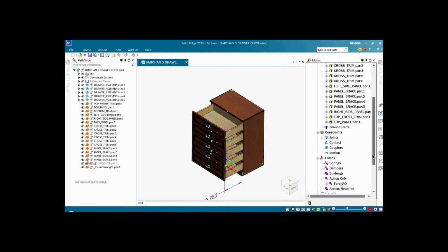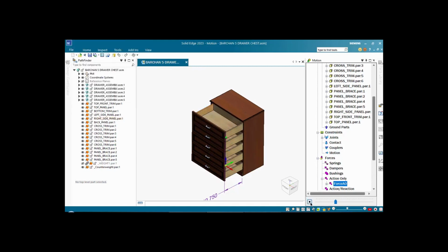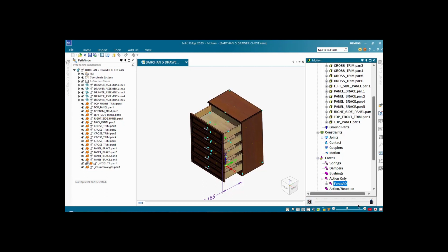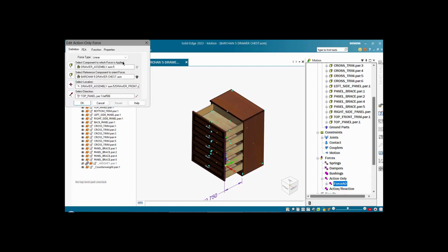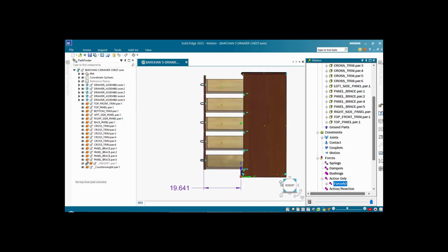So let's go back and define the force as a constant value instead of an expression. Let's give it a value of 75. And now you can see it's tipping forward. We can fine tune it to be exact. Let's do 73. If you look closely, you can't even tell if it's tipping forward or backward. But with the dimension, this is our indicator.